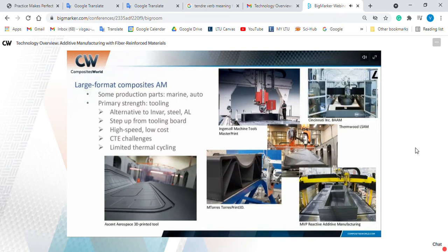the CTE for carbon fiber was larger than that for aluminum. I have to find that out. I think the short answer is yes, but maybe more importantly, the real challenge is predictability. Aluminum is isotropic; it's got the same properties in all directions, and its CTE is predictable. And so in that way, it's probably easier to design for. The CTE of carbon fiber depends on a lot of things: the type of fiber, the type of resin, the fiber loading, and other factors, which make predicting the CTE much more challenging. So I think that's one issue that has to be considered.